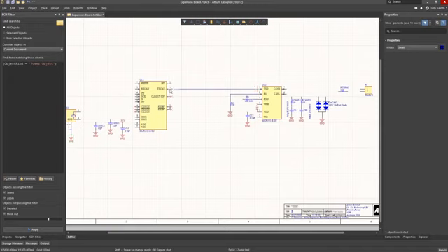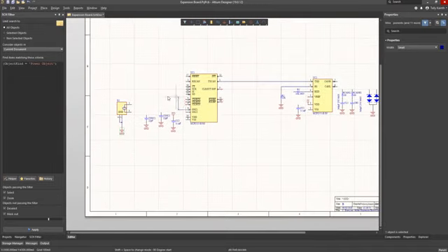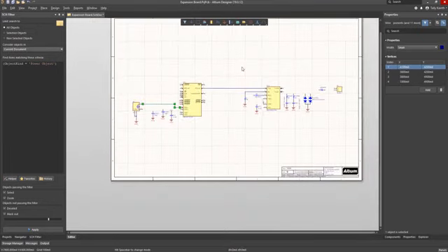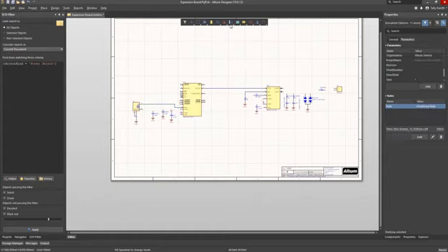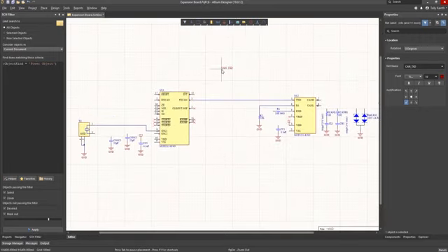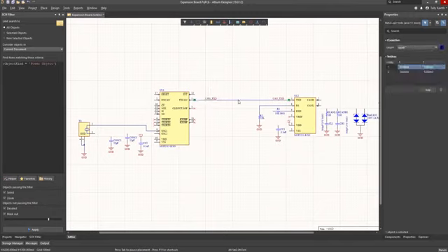Let's add some badly routed wires to illustrate how we can edit them. Individual wire segments can be moved by selecting and grabbing them with the mouse and moving them as needed. To add net labels for circuit readability or for on-sheet connections, right-click on the wire icon and select Net Label. Before we place the label, if needed, we can rotate it using the spacebar, or use the Tab key to access the Properties panel to change the label to the desired net name. Hit Enter to place the edited net label.